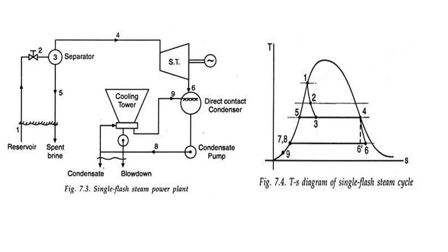From the separator 3, the dry steam at 4 is sent to the steam turbine, and expansion takes place in the steam turbine, and it will be at state 6 in the actual case, and theoretically it may be 6 dash. Then it is taken into a condenser, into liquid form. Once again it is pumped to state 5, and accordingly the cycle is done.